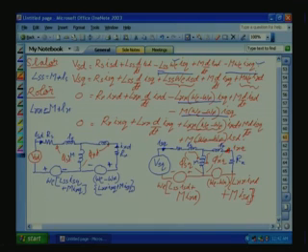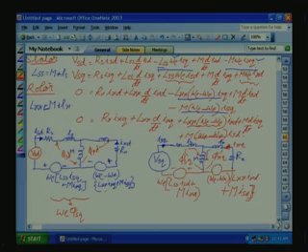This is psi SD, the flux coupling due to LS and M and the current flowing through it. So what is this equation? It is omega rho into psi SQ, this one. And what is this one? Omega rho minus omega r into LRR IRQ plus M ISQ, the total flux, so this is psi RQ. So due to the flux and the rotation, in the Q axis there is a voltage term, in the D axis, stator and rotor.